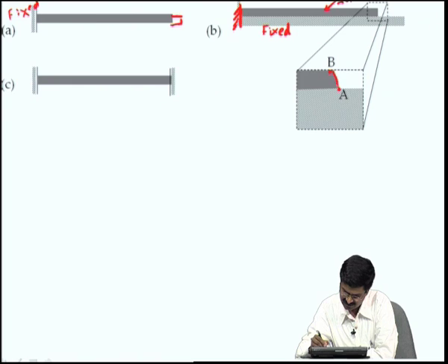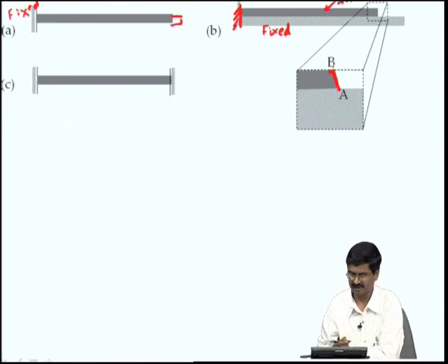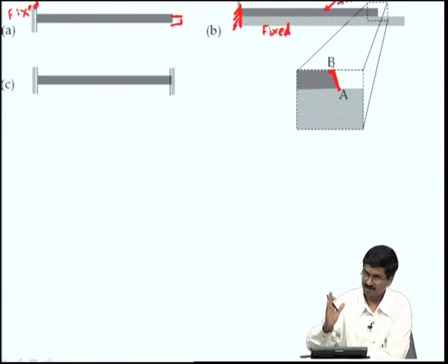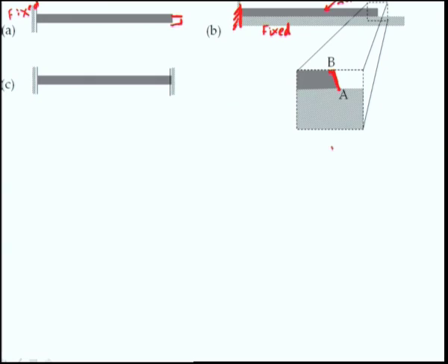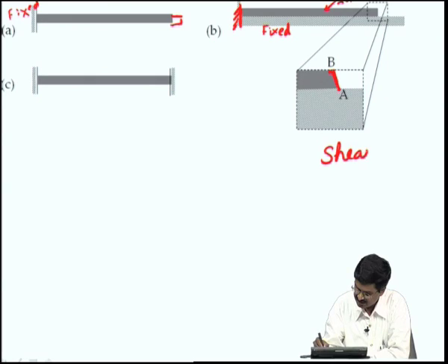So, what you see here is that this surface is actually rotating. Normally, we call something that expands, let us say you have something here and it expands, normal strain or normal stress. When it contracts, that is also normal strain, normal stress. But things can also rotate, as we see here, and that is called shear strain and the accompanying shear stress.